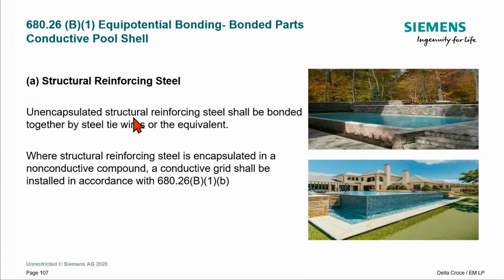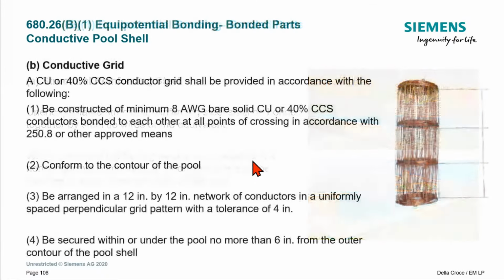And we talked about, okay, structural reinforced steel, again, encapsulated, not going to work. But if we have unencapsulated tie wires, steel tie wires, perfectly fine. Tie it all down. Those guys that do the pools, like as an electrician, we have nothing to do with this. They're already going to take care of all this. We don't have anything to do with it.